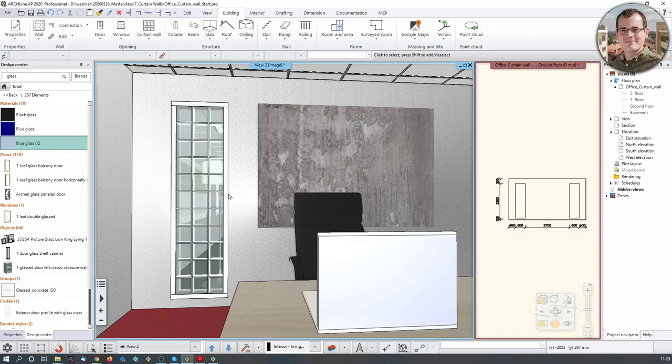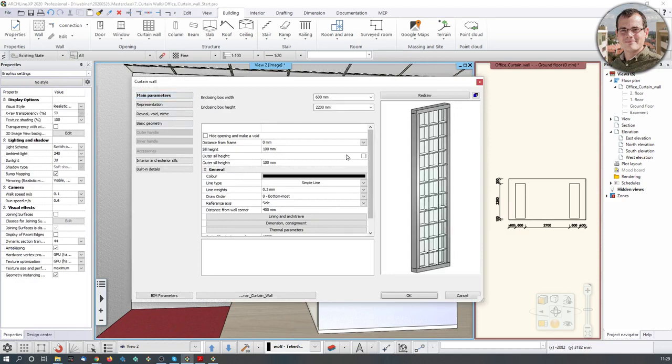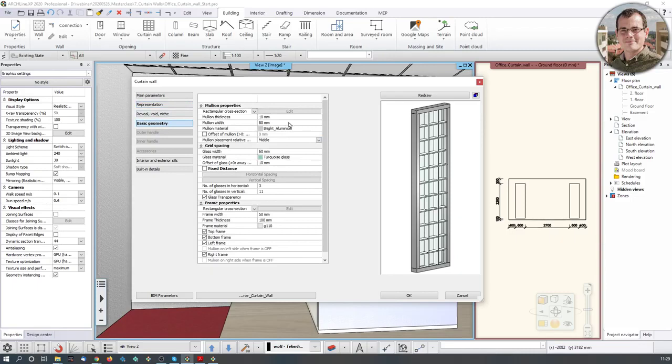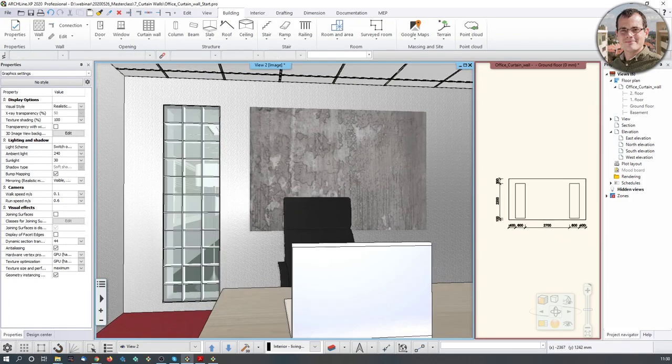Let's just go back to the drawing and say that this I have to change, and the frame thickness should be. Let's just see where I can actually find that. I think it should be frame, and in the beginning I did show you where to change that. I think that was the one. The thickness, yes, here we go. So 10 millimeters instead. Let's just change it to 100. And later on I'm going to look up where you can actually fine tune that. Oh, here we go. So that's what I wanted to achieve. Okay, hit OK. And now I have the right result.